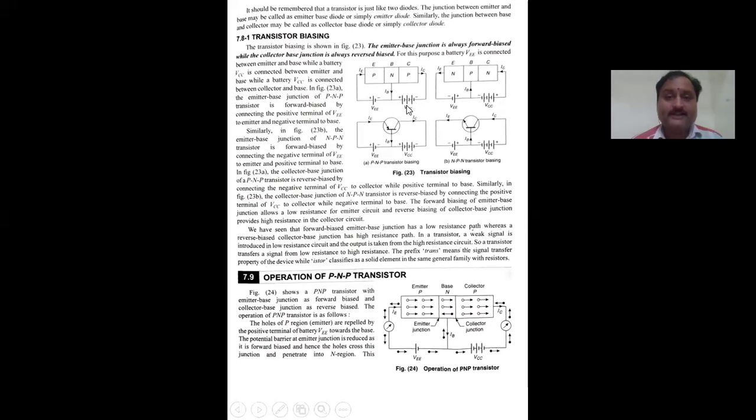Current conduction is through majority charge carriers, in the milliampere range. In reverse bias connection, current conduction is through minority charge carriers, in the microampere range. Why? Because through minority charge carriers, it is difficult to break the depletion layer, so it gets a smaller value, that is microampere current in the reverse bias connection.